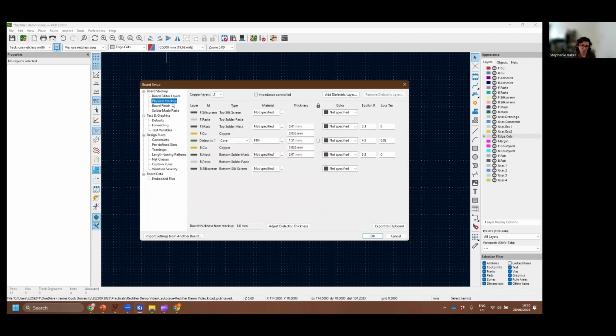You can also change the physical stack up. So as I mentioned before, we will normally be working with single layer or 2-layer boards. Single layer is copper on just the top, for instance. 2-layer would be top and bottom. But you can also, when you manufacture boards through an actual PCB manufacturer, get ones that have lots and lots of layers in between as well. So that's when you could go to 4 layers all the way up to 32 layers in KiCad.